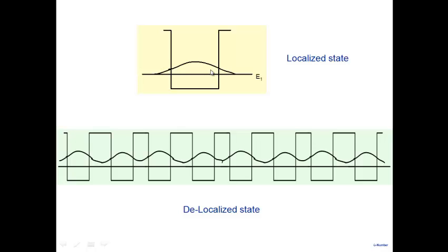We also saw that if you take a quantum well like this and you couple it to several other quantum wells, then as a result of interaction between these wells, what you get is a series of energy states, and the original energy that you see here splits into several energy levels. If you have two coupled quantum wells, you get 2 energy levels. If you have n, you'll get n energy levels, all closely spaced to each other here. Okay, and so this energy level E1 expands into a band.